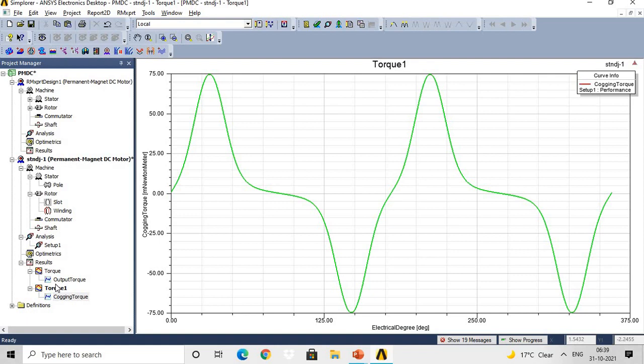First of all, you need to select the type of the vehicle, like 2-wheeler, 3-wheeler, 4-wheeler. Then you need to go through the design part for selection of the motor size for the EV application. You need to go through that calculation, and you need to select the rating of the motor, that is, at what speed, and what will be the size of that motor, etc. And then you can do the simulation, and through the performance curve you can decide whether your DC motor is fulfilling the requirement for EV application or not.